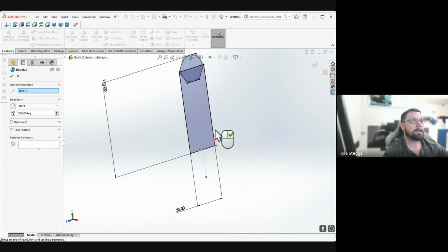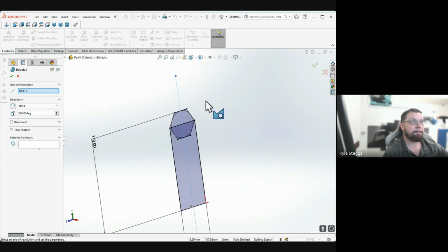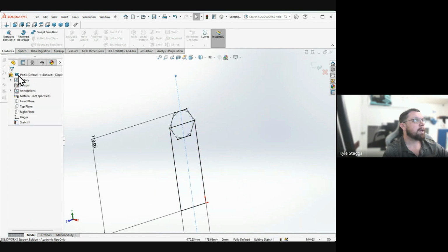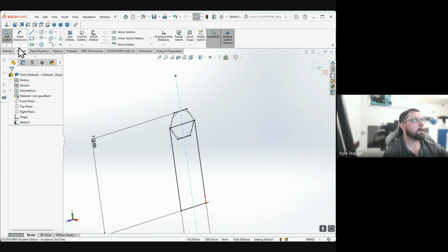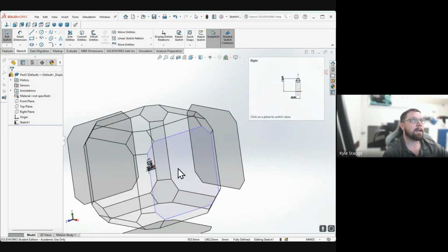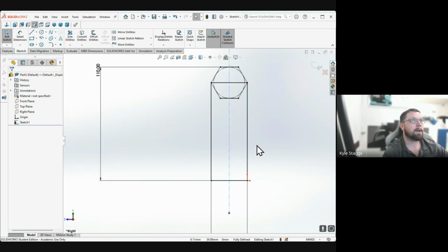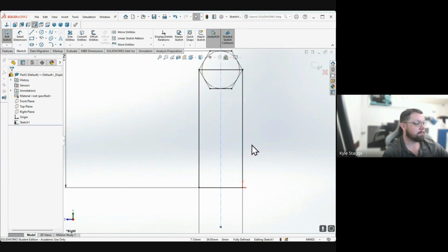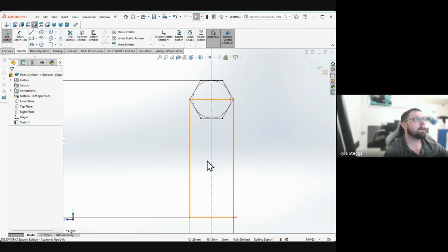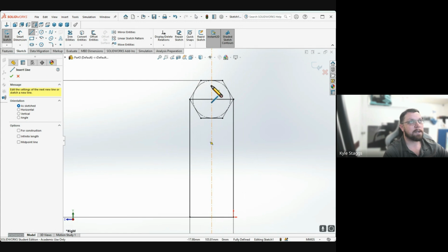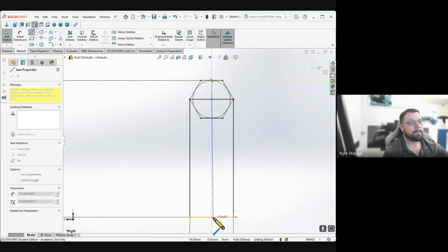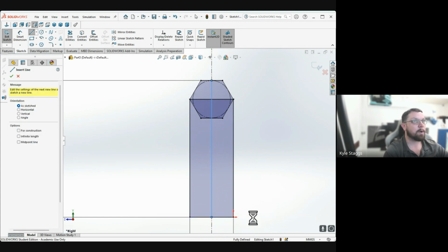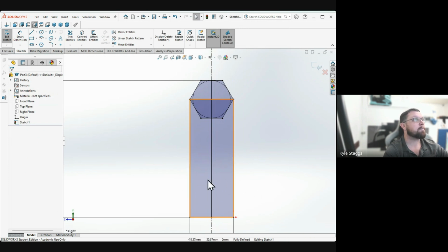This is where we're going to come into a problem, but we are going to need a bisecting line. So I'm going to go back to the sketch, and I can add this on an angle without ruining everything in the universe. If you try and start getting fancy and adding center lines when you're not looking squarely at the sketch, you're going to cause yourself some headaches because you're going to miss some references.